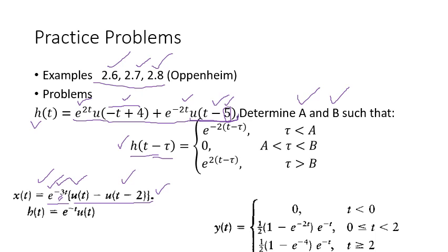Beyond 2, this signal will be 0, so multiplying this with this will result in 0. So you have a very brief duration input signal, and this signal is infinite, right? You understand, e to the minus t multiplied by u of t. When it's multiplied by u of t, that means t cannot have a negative value, because if t has a negative value, u of t will be 0, and you multiply this with this one, so your response will be 0.